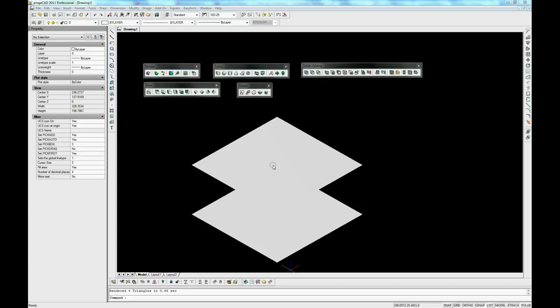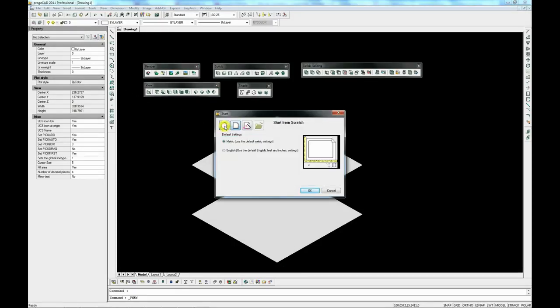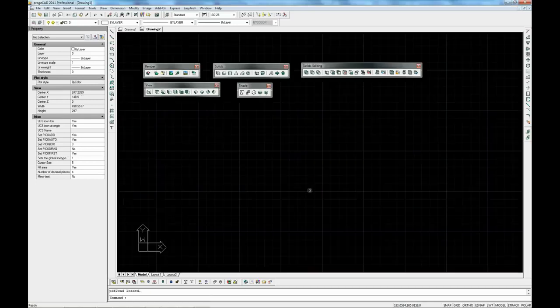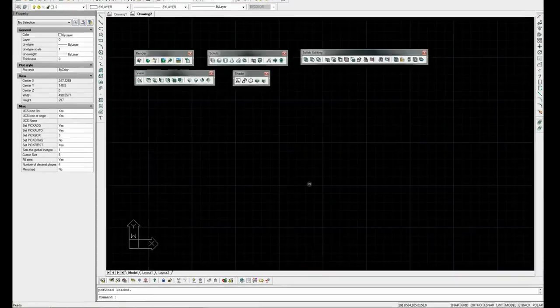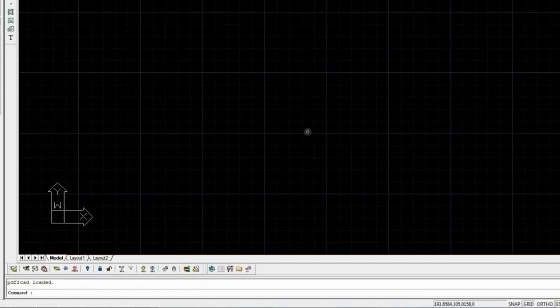In progeCAD, surface models consist of edges and surfaces between these edges. Surfaces are simply polygon-based wireframe meshes. progeCAD allows you to work with surfaces in a number of ways. The first method involves applying thickness to your 2D planar entity.